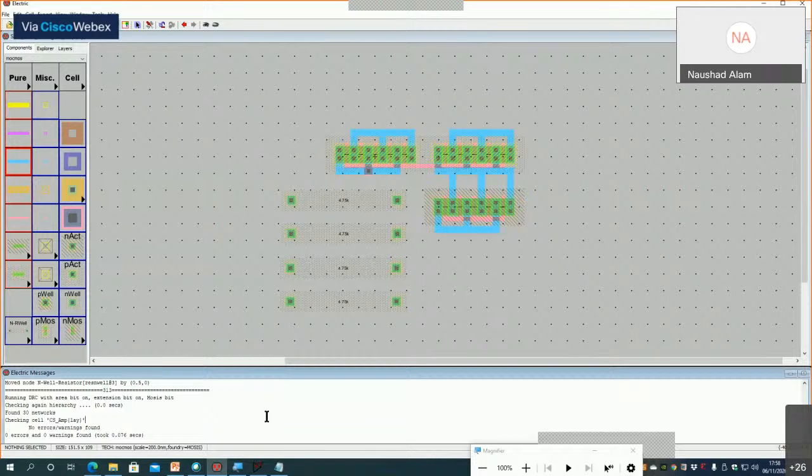Now you can actually see why in circuit design, particularly analog circuit design, we have been taught to avoid using passive components in our circuit, right? You can see that 3 of our transistors are consuming a relatively smaller area as compared to the area consumed by this one resistor of 19 kilo ohm.